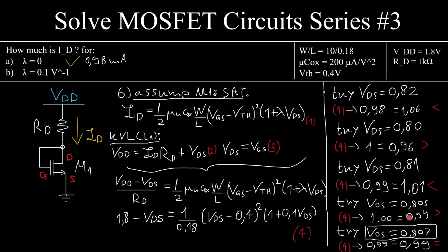All right, I take this value, I check, is this higher than VTH? Yeah, it is, so my saturation conditions should be satisfied. This is always, we said that it is always true. This is satisfied, all right, VDS is the same as VGS, which is higher than 0.4.